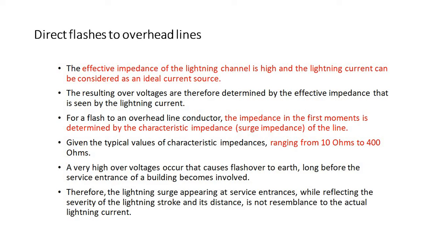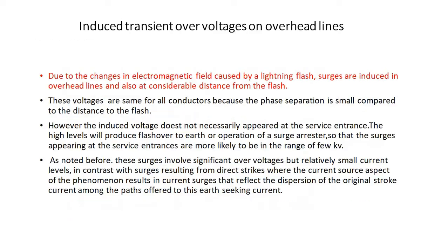A very high overvoltage occurs that causes flashover to earth long before the service entrance of a building becomes involved. Therefore, the lightning surges appearing at a service entrance, while reflecting the severity of the lightning stroke and its distance, do not resemble the actual lightning current.